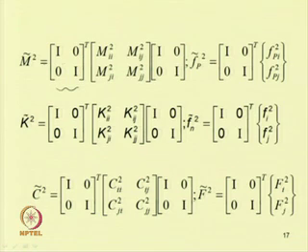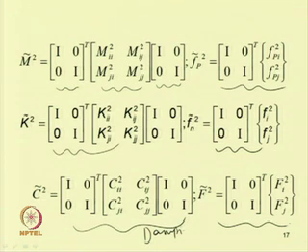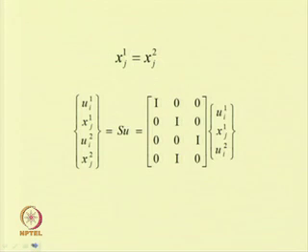So, this is 0 I 0, 0 I transpose, this is the mass matrix, into I 0 0 I. Similarly, the forcing function can be written by multiplying with the transpose of I 0 0 I. Similarly, this is the K 2, this is for the nonlinear force, this is for the external force, and this is the damping matrix. So it is changed in this way: the damping master matrix, the stiffness master matrix, and this is the mass matrix of the master component.